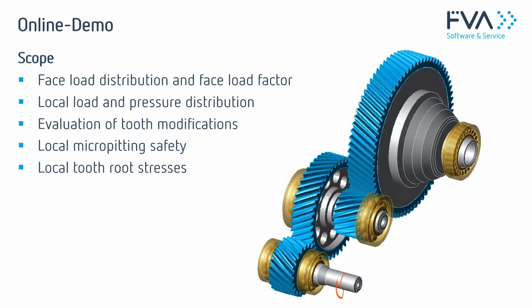In the online demo, I want to show you how to calculate the face load distribution and the face load factor over the face width. So this is the basic method for evaluating the tooth modification. Then I will go on to the local calculation of the load and pressures. I will evaluate tooth modifications to achieve a good load distribution on the tooth length. Then I will calculate the micro-pitting safety and the local tooth root stresses as well.